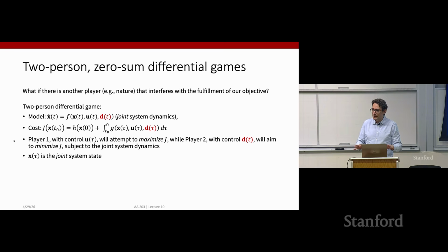Here, we're in a deterministic setting, but d encodes the notion of another player, think of it as nature, that is trying to interfere with our objectives. These are the so-called adversarial formulations for optimal control that are very useful to come up with control policies that are really robust. No matter what nature throws at you, within some limit, you're still guaranteed, if you use the techniques that we're going to explain, to achieve your objectives.